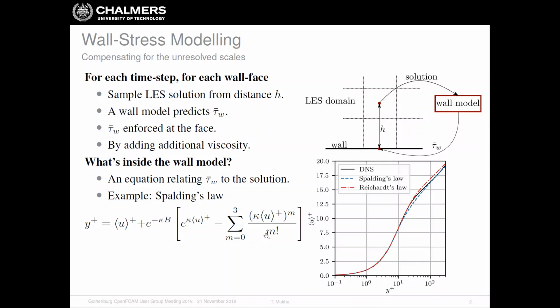So there are many ways of doing wall-modelled LES, and one of them is called wall stress modeling, and this is what I'm going to focus on in this talk. Probably it's safe to say that that is pretty much the most widespread way of doing wall modeling. For wall stress modeling, we're going to apply the same procedure at each time step and at each wall face of the simulation. This procedure is basically summarized in these 4 steps.